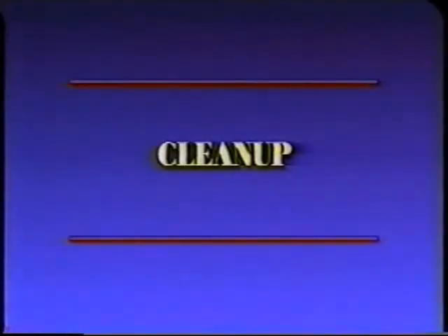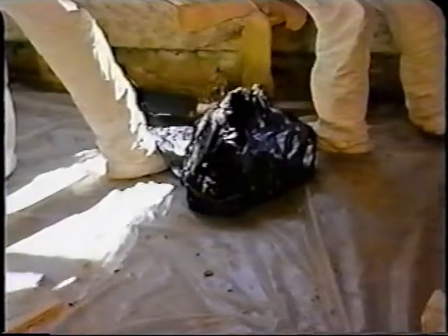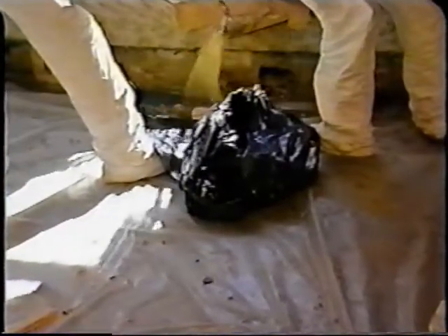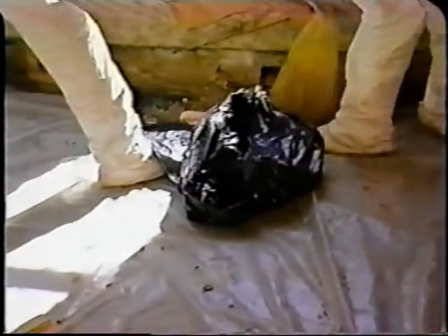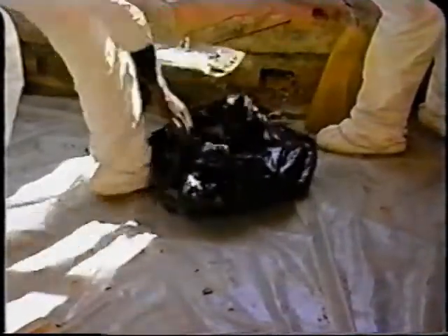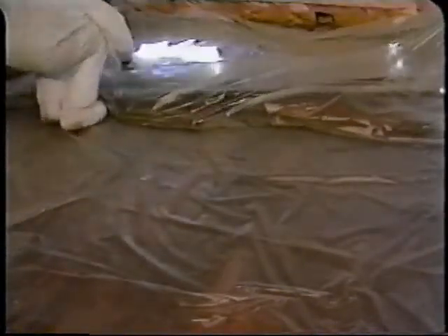All lead hazard control activities can produce dangerous quantities of leaded dust. Unless this dust is properly removed, a dwelling unit may be more hazardous after work is completed than it was originally. Throughout the project, periodic cleaning should occur and debris should be carefully removed from the premises. Contaminated bulk debris, such as doors, windows, and baseboards, should be removed from the job site on a daily basis.